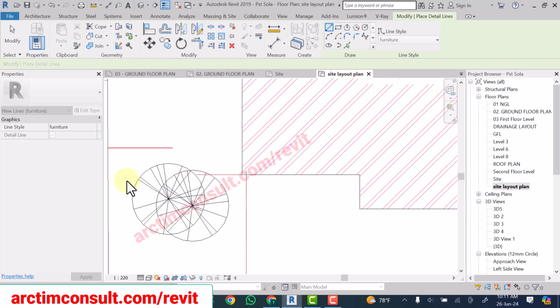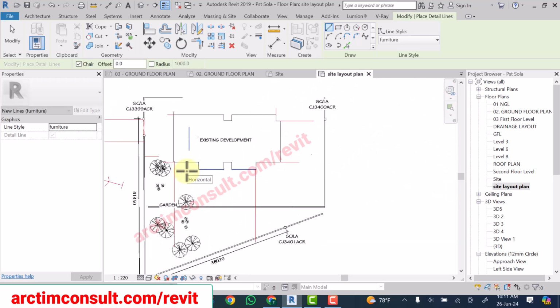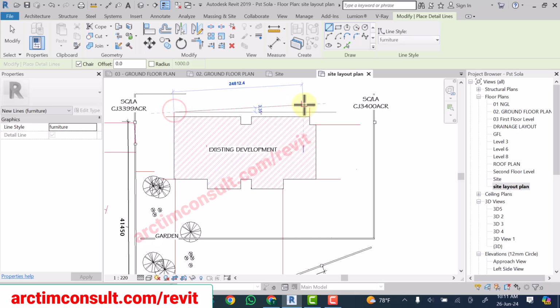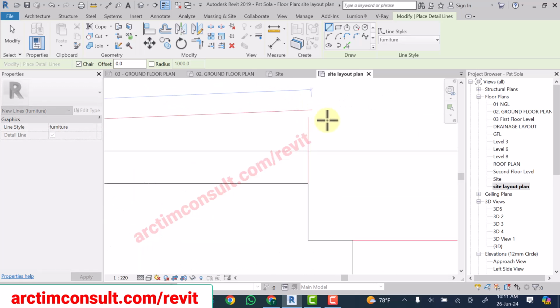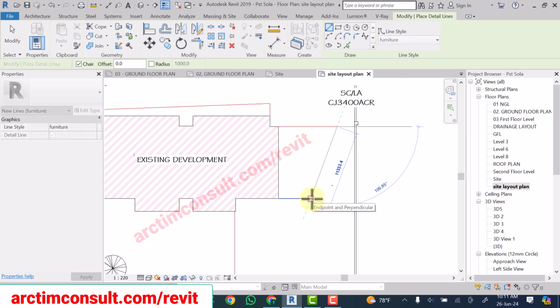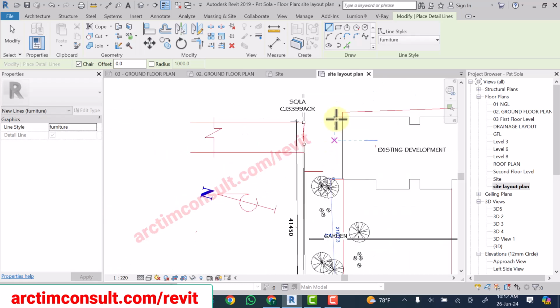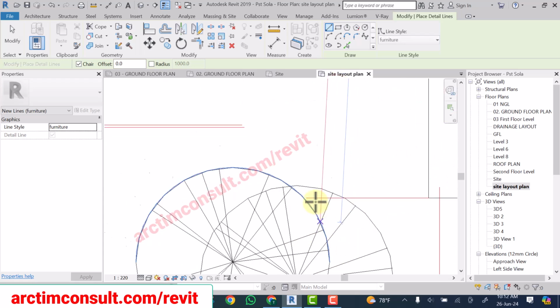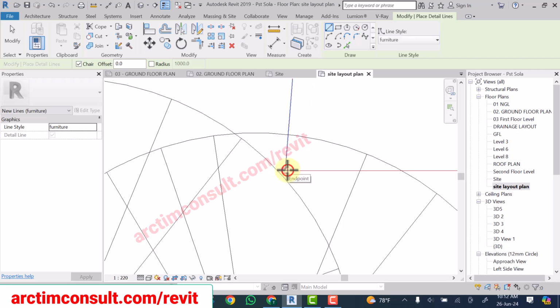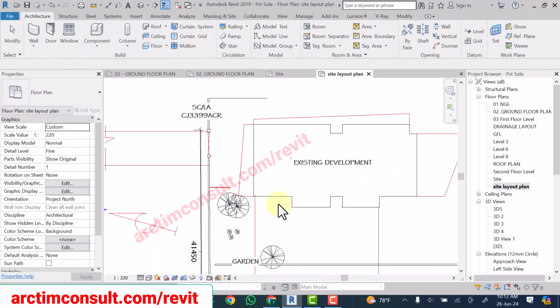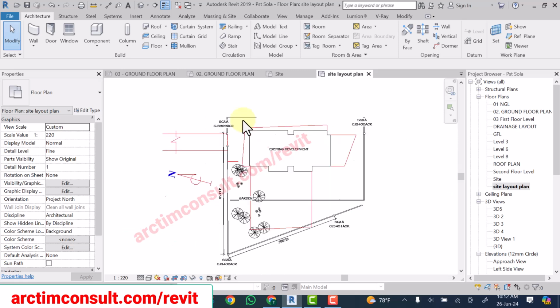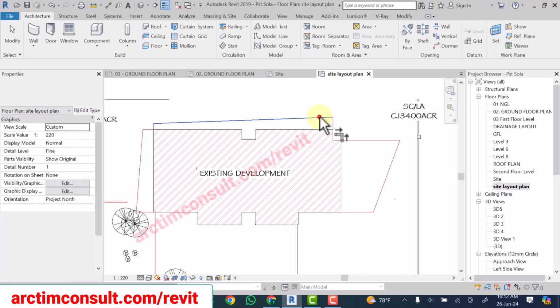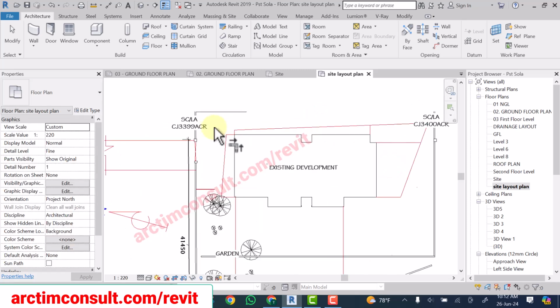All right, now that we have all the edges mapped out, it's a question of connecting them with lines. So I'll simply connect all the edges with lines, and you will be fine. Okay, now let's use our trim to corner to blend the edges together.